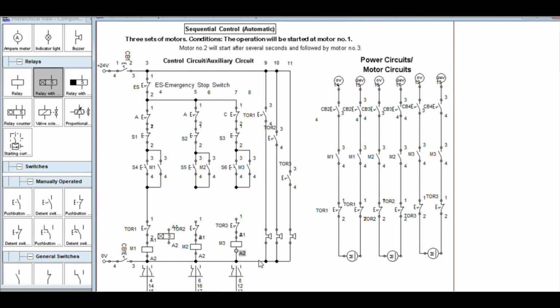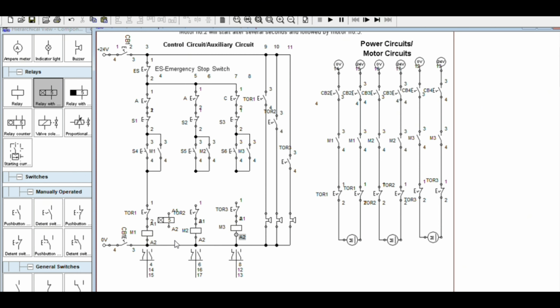Okay, the numbers at the bottom, you may wonder if it was already explained in the previous circuits. This one is normally open, and you can find them at line 4, 14, 15. So line 4, one normally open of M1. Line 16, you can find M2. Line 16, you can find M3. So because this will create lines when you do vertical lines. That's it. And when we are going to place a normally close contact, it will be also here.